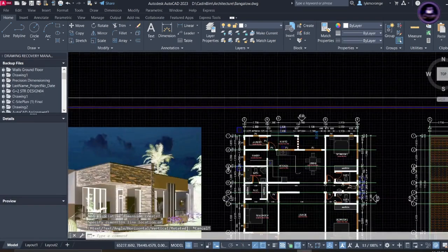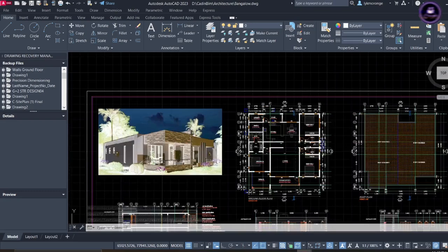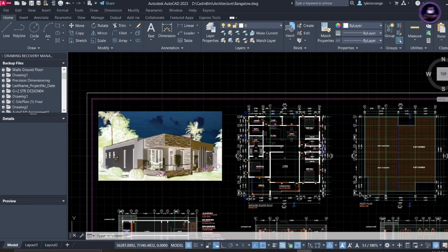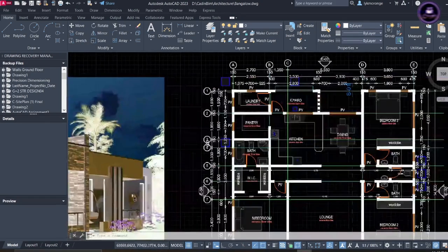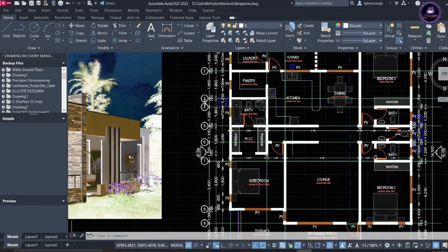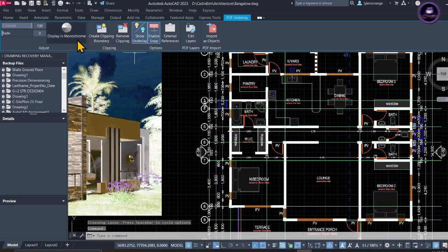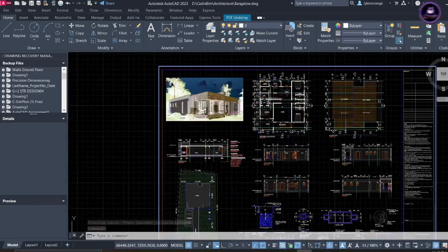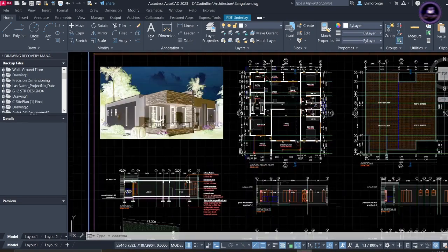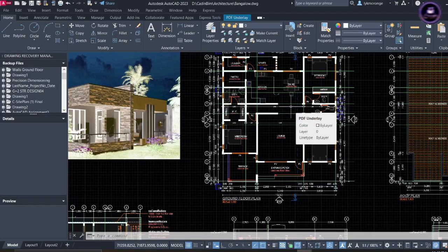So once we get our scale right, the next thing we have to do is separate the part that we really want to work on, which is this part here. You can just model it while it is here, because this is just an overlay, a place that you can trace. It's not that we just imported this PDF, like you cannot select and delete anymore, but you can trace on it. So to do that tracing, we have to trace our grids. We also trace beams here, meaning the walls, which will be creating our beams. Then also input our columns.